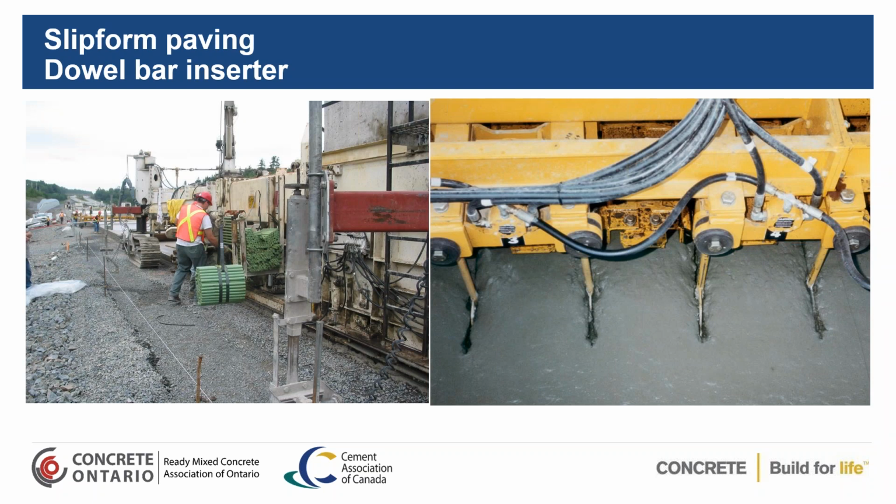Now, another option to having dowel baskets is to actually have what's called a dowel bar inserter. The left-hand picture here shows you dowel bar inserting equipment, and they're loading the dowel bars onto the equipment so that the person operating the paving machine can put those dowels into place, and then the machine loads them, puts them in the right 300 millimeter spacing, and vibrates them down into place.